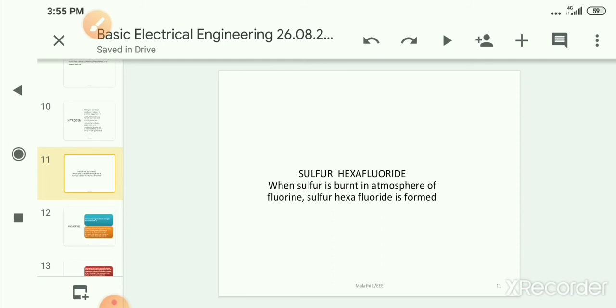It has many advantages as an insulating gas. SF6 is a main gas. It is a very popular gas insulating material. The dielectric strength increases with increase in pressure. Hence, it must be used under high pressure. So sealed tanks, gas ducts, all those are required for construction, capable of withstanding high pressure.